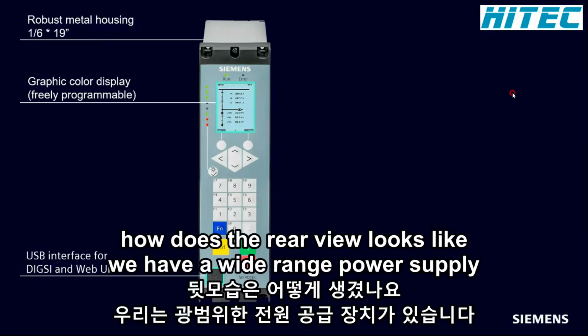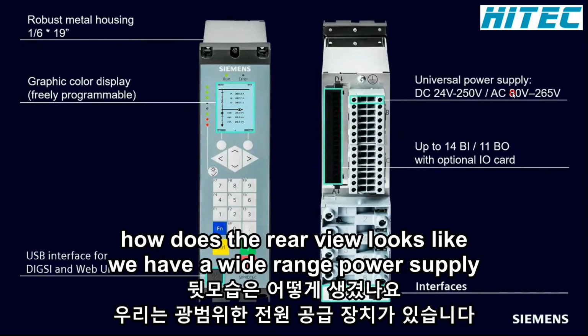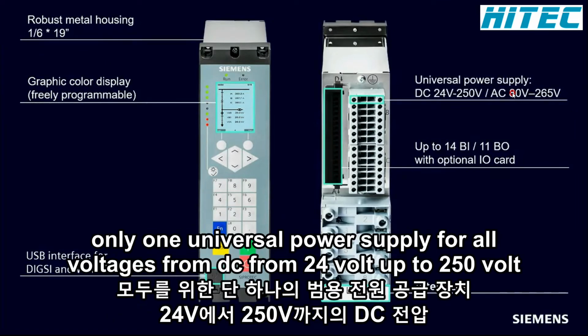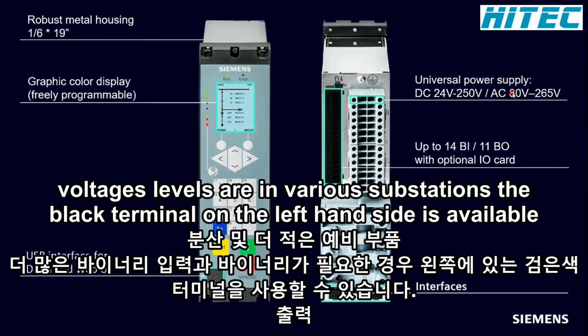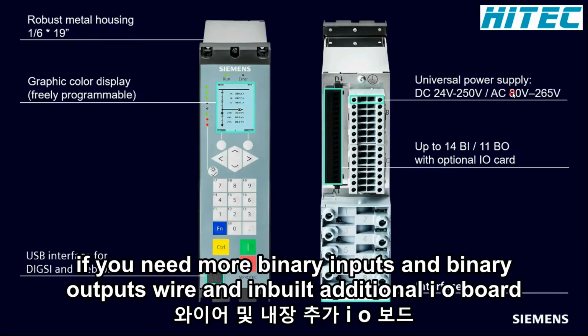How does the rear view look like? We have a wide range power supply. Only one universal power supply for all voltages. From DC 24 volt up to 250 volt, AC 80 volt up to 265 volt. This reduces the variance and less spare parts if different voltage levels are in various substations. The black terminal on the left-hand side is available if you need more binary inputs and binary outputs via an inbuilt additional I/O board.